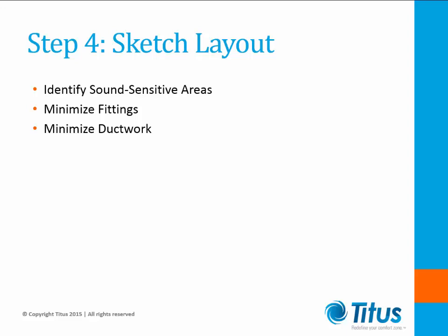When sketching out the one-line ductwork, minimize fittings. Fittings increase both cost and sound of the duct system. Avoid close-coupled fittings, as duct pressure losses increase dramatically in these cases.